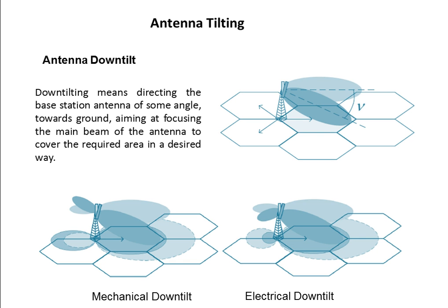So antenna down tilting is one of the very important exercises for directing the radiation within the required area as well as to avoid interference in the non-required area. There could be two categories of tilts in an antenna, as we all know: mechanical tilt or electrical down tilt. Mechanical tilt is nothing but just inclining the overall body of the antenna. So once you incline the front lobe towards the ground, at the same time you are declining the back lobe of the antenna towards the space.